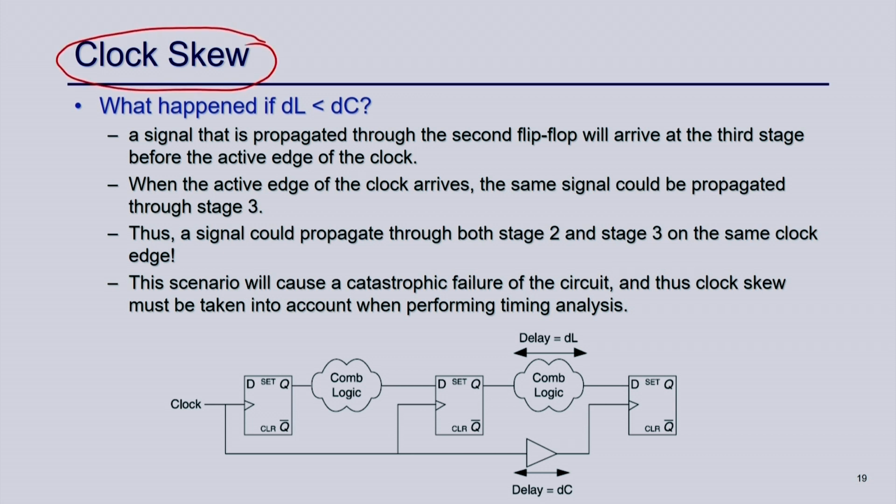What is clock skew? The same clock is feeding all the registers of your circuit, right. Suppose your circuit has only one clock, not multiple clocks. But our expectation of a synchronous circuit is that that particular clock will reach all the registers at the same time, right.